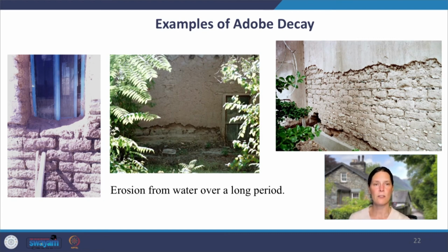The natural earth plaster, made from the same material as the bricks or cob, plays the role of pulling moisture out of the wall, strengthening and protecting the brick, so that the bricks continually dry to the outside of the plaster, even after rain. There are houses, mosques, and churches around the world that are suffering the effects of concrete stucco over earthen construction. Many are now trying to revert to the traditional practices.